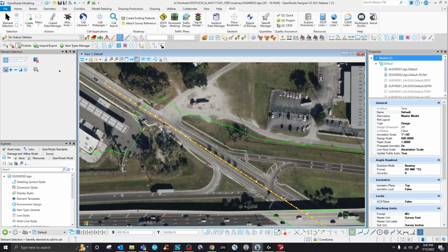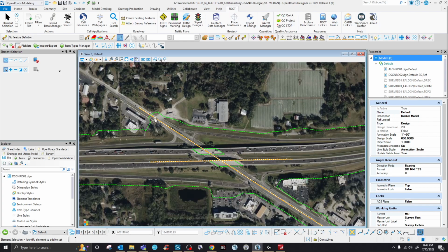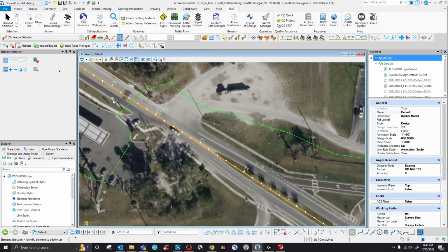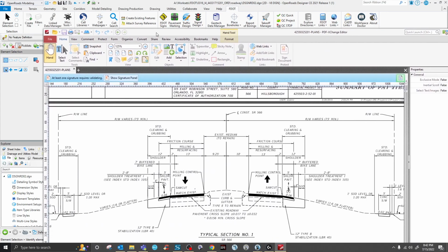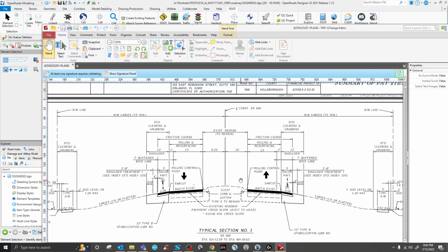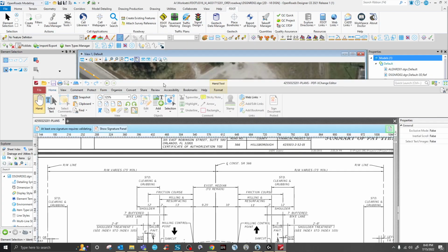So what we're gonna start is, I'm gonna show you how, typical section 1, let's do that. So we have this typical section, see this one? We have the dimensions here, we have 10, and then the road is 13, and let's just make it 15. So we wanna do travel lane 15, travel lane 15, and we need to go from the center 9.25 and then 10.25.